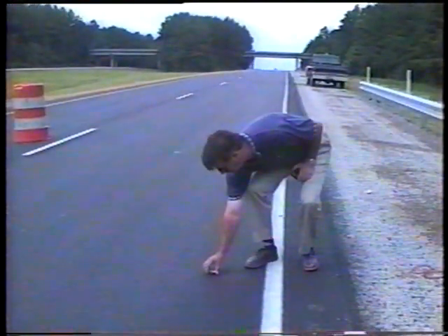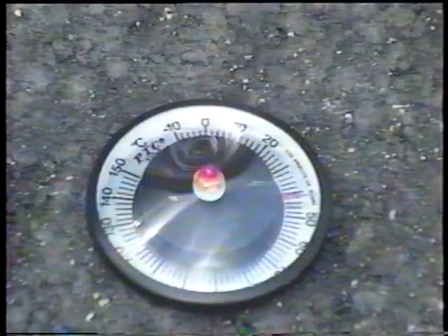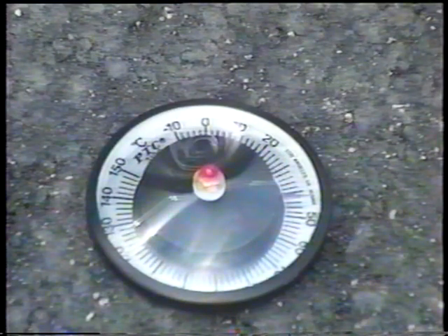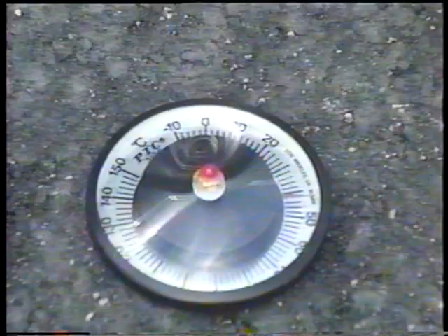Cold temperatures, of course, will cool the mix, making it difficult to get adequate compaction. In addition, the fresh mat may not adhere to a cold surface, so always check the actual temperature with a reliable thermometer. You should also be aware that many agencies have calendar date restrictions, such as no paving allowed after October 15th, or before April 15th. These restrictions are provided to help prevent the problems associated with low temperatures. Again, be sure to check your agency's specs.